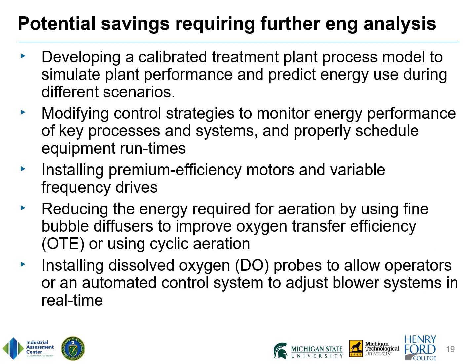Some energy-saving methods, such as those shown here, require further engineering analysis. These include developing a calibrated treatment plant process model, modifying control strategies to monitor energy performance, installing premium efficiency motors and variable frequency drives, reducing the energy required for aeration by using fine bubble diffusers, or installing dissolved oxygen probes to allow operators or an automated control system to adjust blower systems in real time.